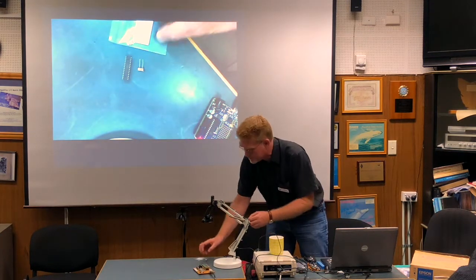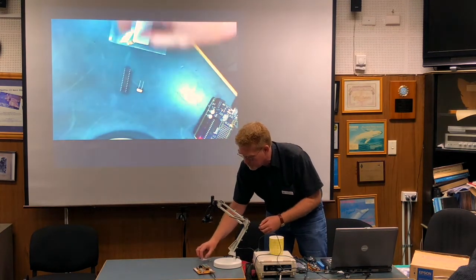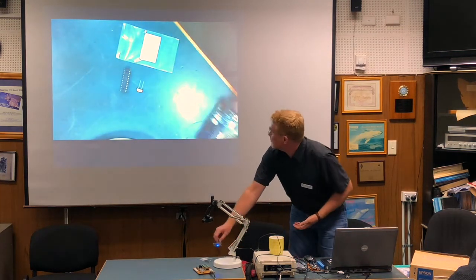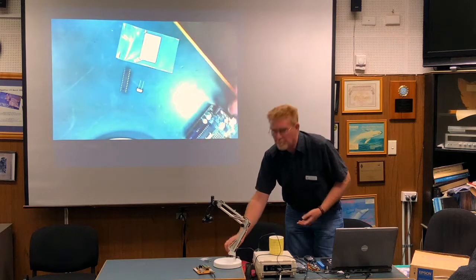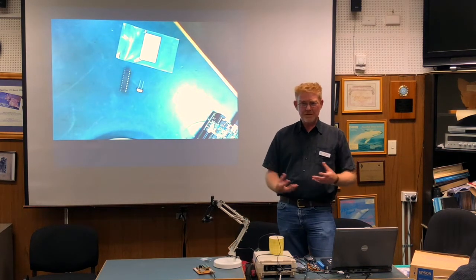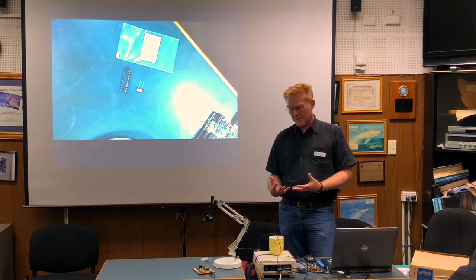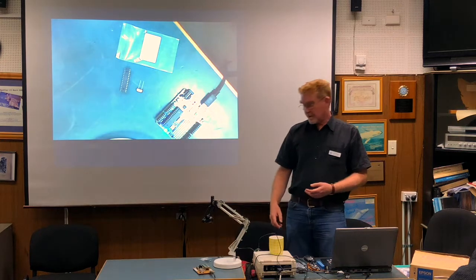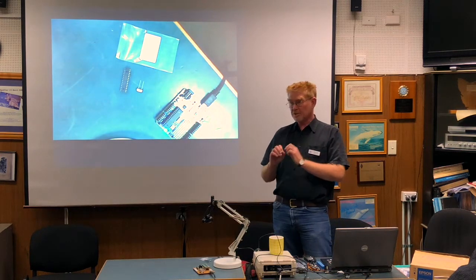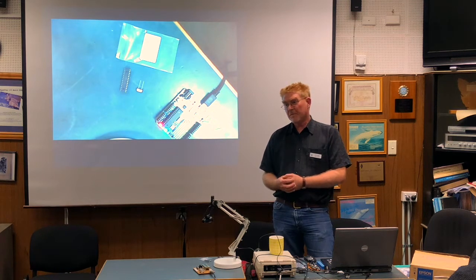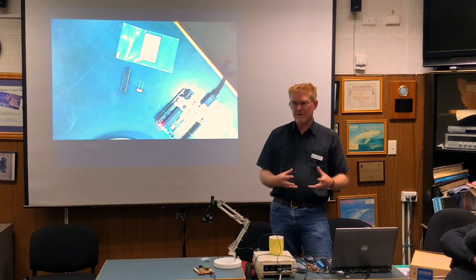If you're so inclined, you can build your own Arduino from scratch. Now, I wouldn't recommend you go off and try to build something like this, but if you're comfortable writing code for the Arduino environment, you can develop it using all the tools on your desktop PC on one of these larger boards, and then you can download the code into the chip, pull it out and build it straight into the gadget you're working on. That could be useful for things where you're never going to go back and change the code again, or something that's going to go in a small box because you have space issues.